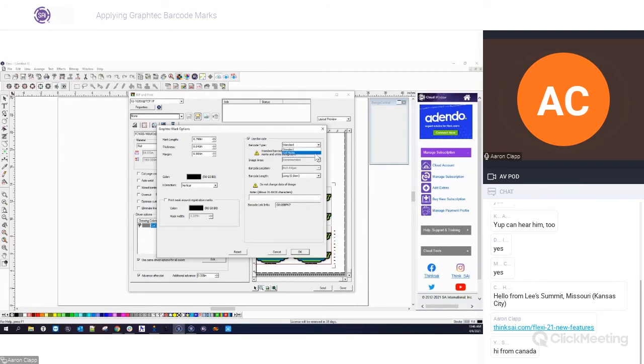Now, if we go back here and set the roll media, we've got several different options here. We've got an image area. Now, this image area is set to recommended. If you decide to change this to maximum, this is something you'll need to define on the cutter itself. So this is kind of a cutter mirror setting. So essentially what this means is whatever you have set on the cutter, you're going to want to duplicate here, which typically is going to be recommended.